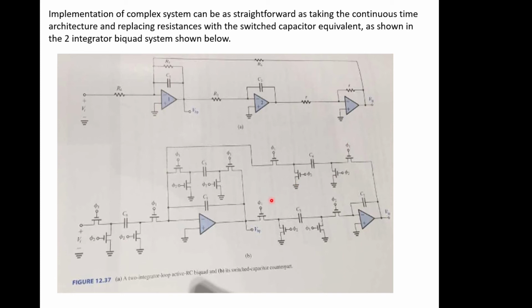So the overall accuracy of the frequency cutoff of this system as a filter is now pretty much defined by the accuracy of the clock that is being used to generate the switching frequencies for this. So you can put all your time and effort into making a really, really good, highly accurate clock, and the rest of all this stuff will just follow accordingly. Everything is synchronous. It's quite nice. So you can see how these ideas are starting to come together now.